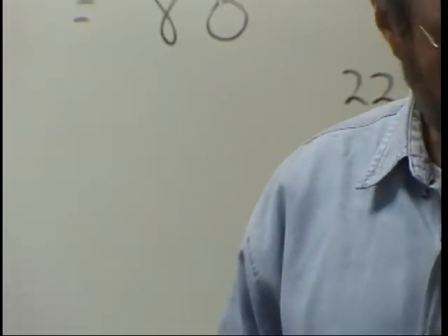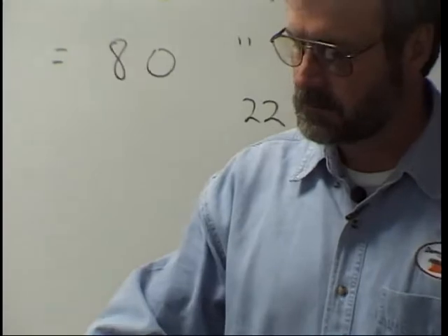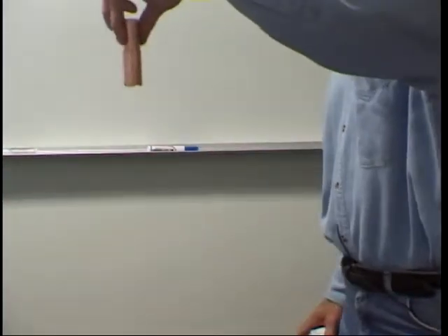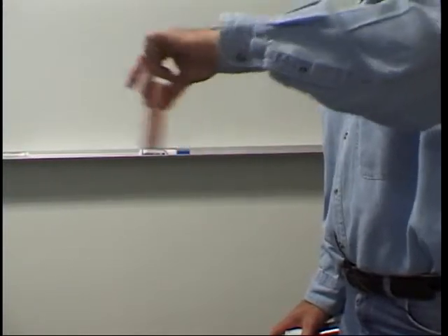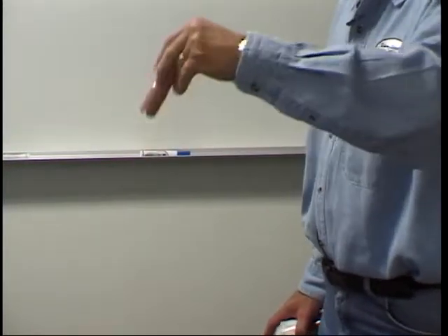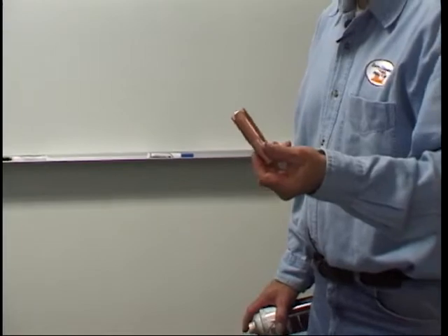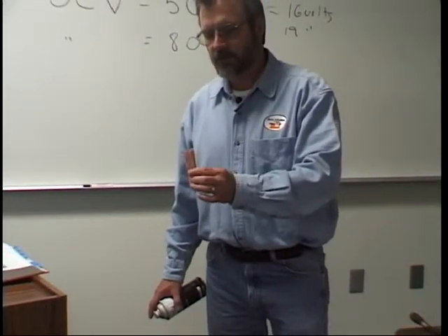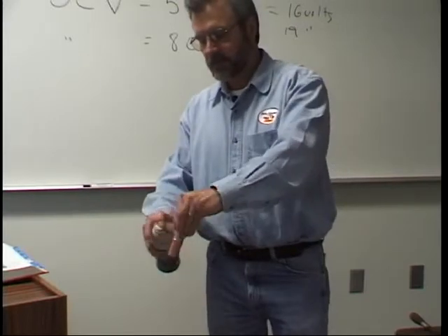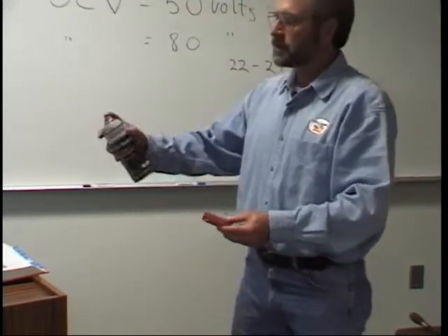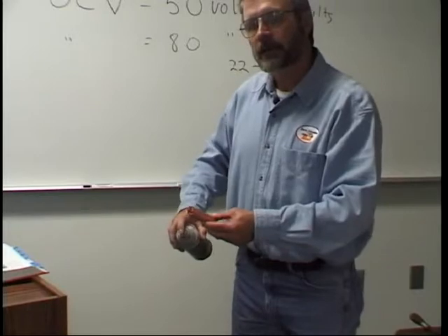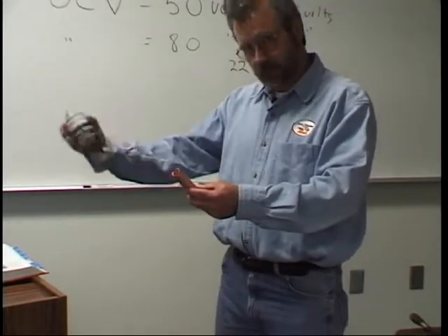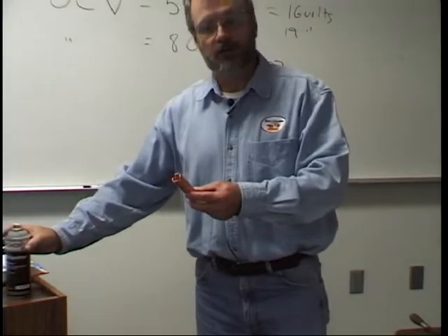And it's just a spray. Shake the can a little bit. Spray it in there like that, and then just dip it up and let the excess drip off. You don't want to get it over on your weld. It won't really hurt it, but I always had a fear of dropping liquid stuff in there. Typically it'll vaporize beforehand. Sometimes we'll spray around the outside, and also you can spray it on whatever you're welding, and that will kind of form a coating that will keep spatter from sticking to whatever it is you're welding.